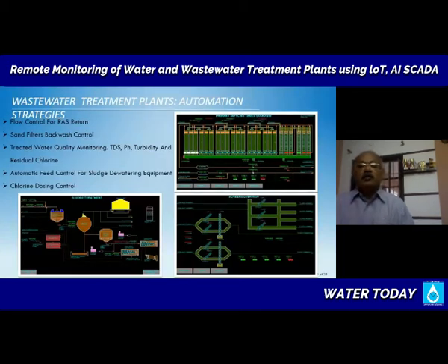So this is in terms of wastewater systems, and of course for the sewer systems also, you can have a SCADA type solution where you monitor all your pumping stations, each and every pump operation, and see whether any pump has failed or there is a power failure here or there. What is the capacity in your sewer system? If you are putting some flow meters in your gravity sewers, you are able to see whether your sewer is overloaded or not. If your treatment plant has a failure and is not available for some hours, how much water can your sewer system hold? These kinds of operational considerations can all become very visible instead of getting hidden below the ground.